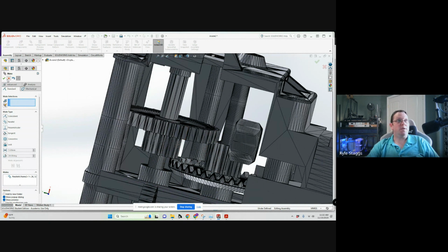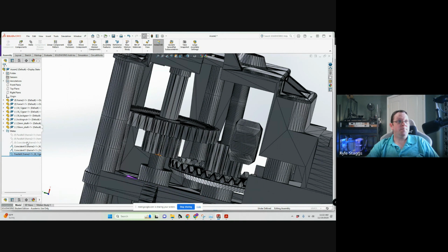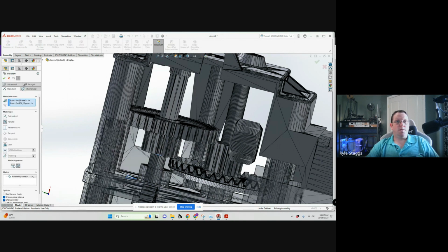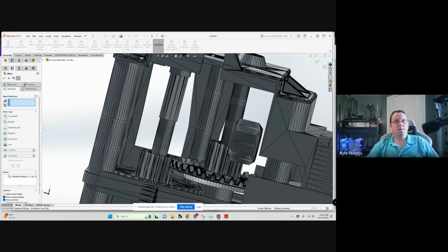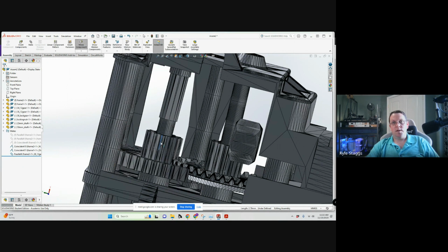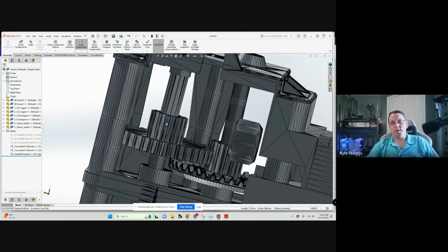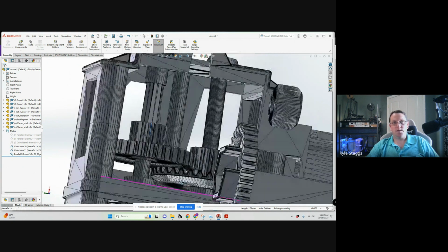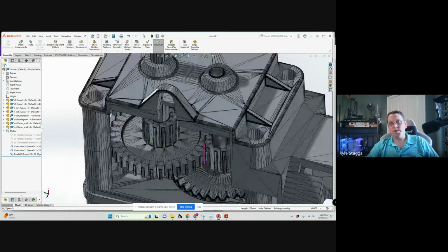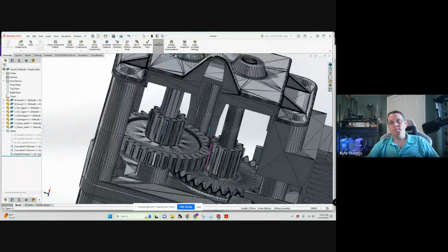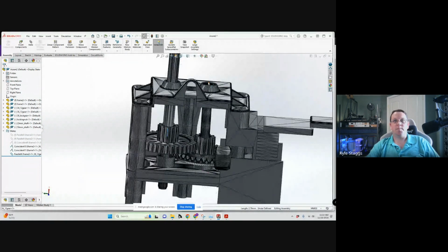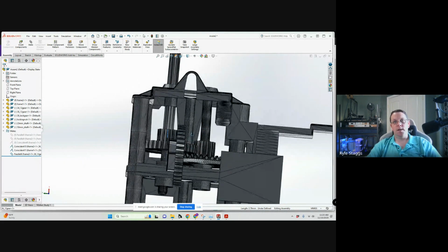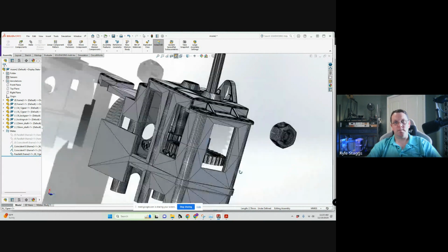So what you actually have to do is do an anti-parallel, do a flip, and bring this up so that if you wanted to run it, you have to run it like this, where you have clearance underneath the gear, you have mesh in those teeth, and once everything is properly square, without some of the alignment issues, concentric, you'll have good meshing and you won't have the same kind of clearance and gear lash issues.